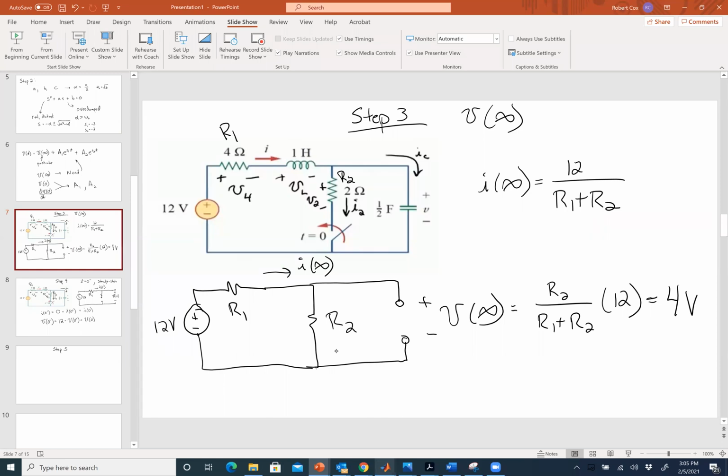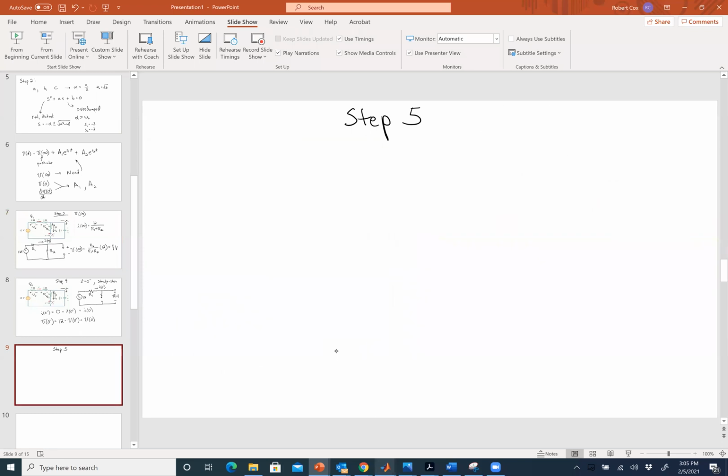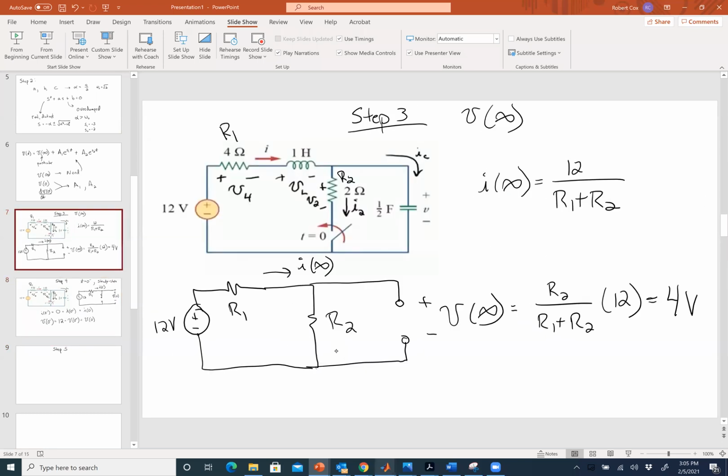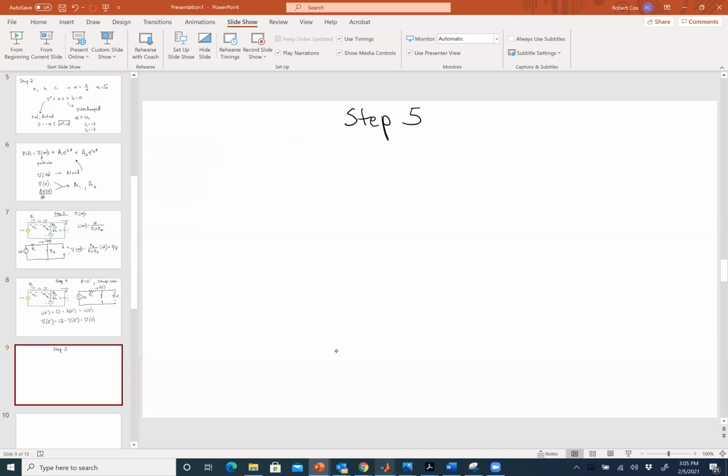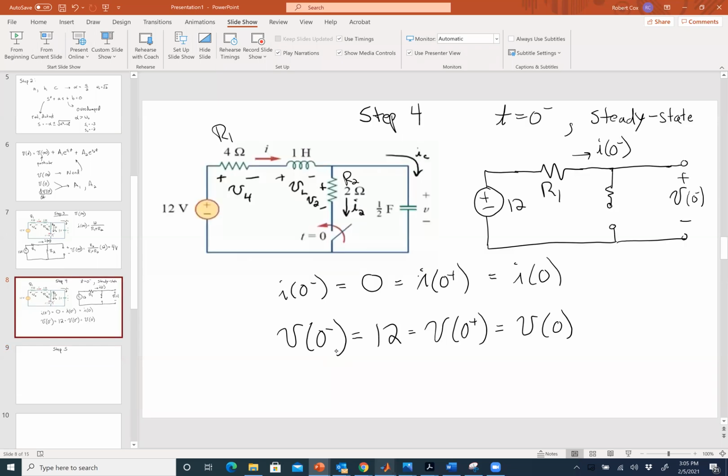Yeah. So basically the circuit looks different at those two instants. At 0 minus, the circuit looked like just a big open circuit with no current flowing through it. The 0 plus condition is a different one. The switch has moved, but the issue is that the current in the inductor is constrained.